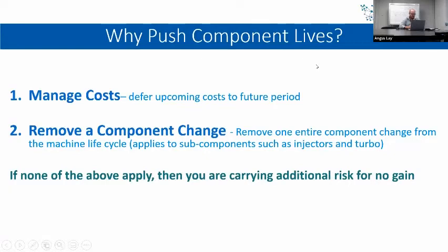So potentially target life might be 24,000, but on that fleet you could eventually be changing some of those components out 6 or 12 months after they achieve that target. So there are those risks that you want to manage, all those reasons to push those components so you can change them out of the planned state.